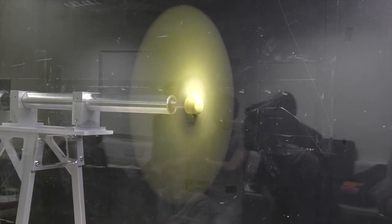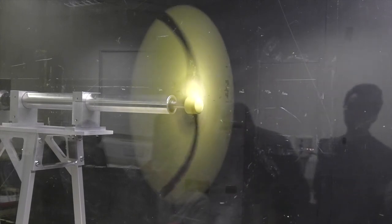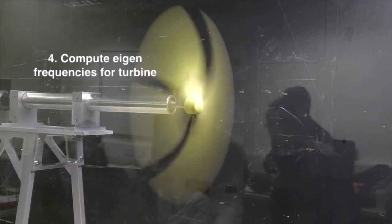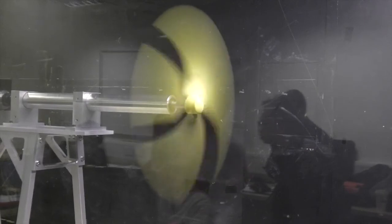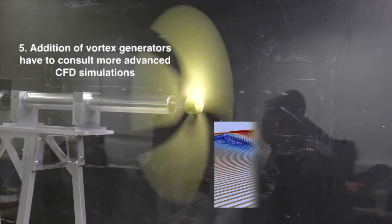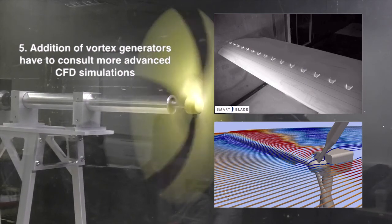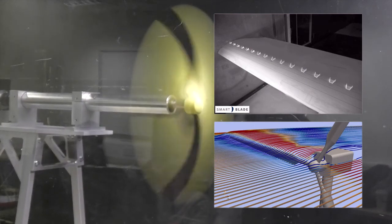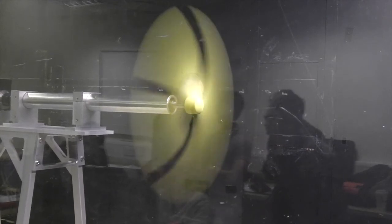The ability to manufacture hollow blades with an I-beam structure, as commonly used in the industry, would also enable a lighter design. Vibration analysis can be carried out on our turbine via computing the eigenfrequencies of the turbine numerically. In an effort to prevent flow separation, vortex generators could be added onto the surface of the blades. This, however, requires some sort of flow visualization in order to be aerodynamically effective and not simply added mass. This is beyond the scope of our knowledge during the design stages.